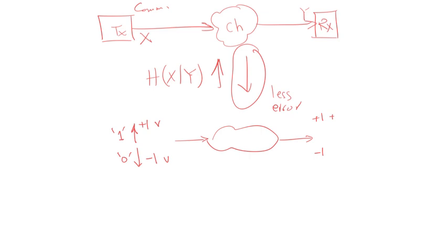And that noise, by the way, has some distribution. We call it a Gaussian distribution or a normal distribution, right? And it can take any value from minus infinity to infinity. Realistically, of course, in an electronic system, if this electronic system is operating on a 5 voltage source, then it can take any value from +5 to -5. It cannot go beyond what the source is doing, right? Because there is no source to bring higher voltages, okay? So sometimes I will receive this plus maybe a 0.1 volt, or maybe receive this minus 1.2 volt, for example, right? Depends on what's the noise value.